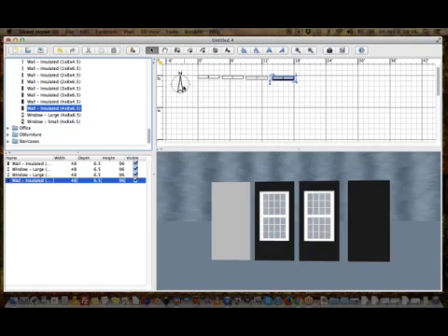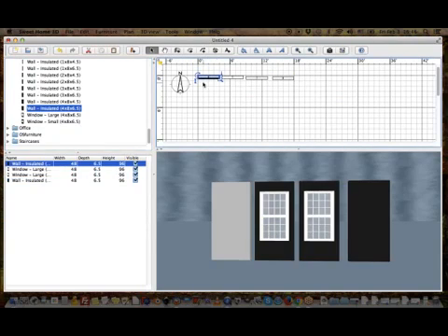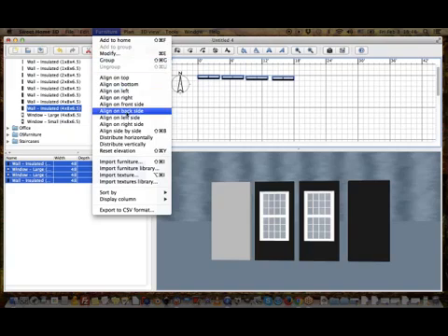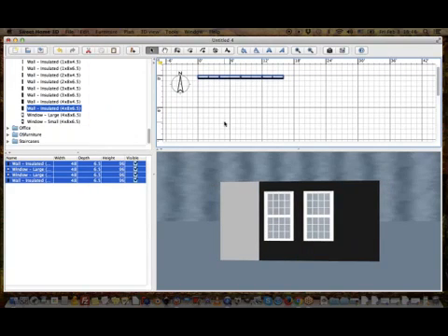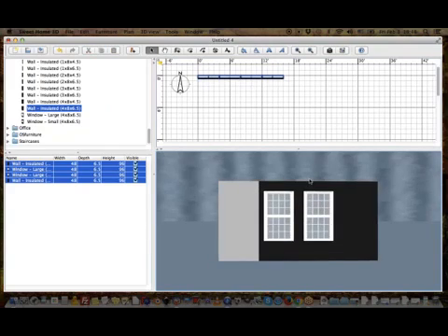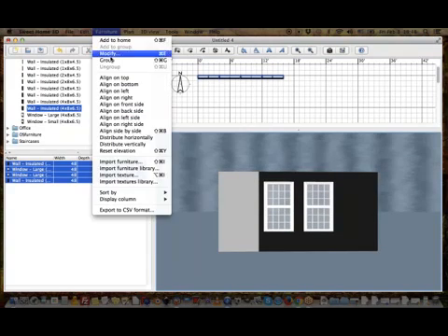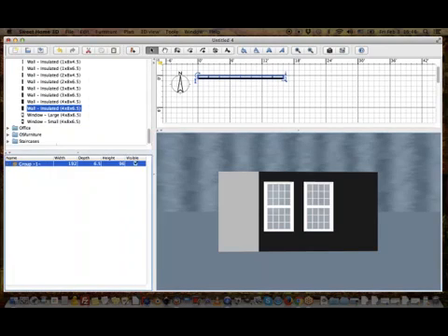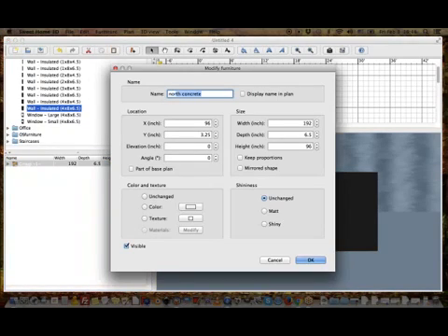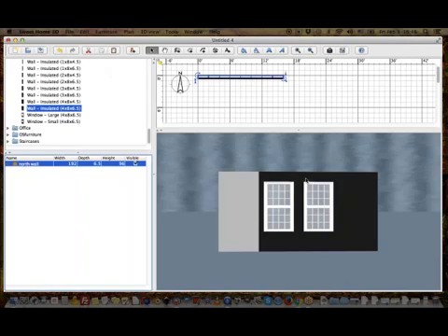If I want to have a perfectly straight wall, I start by selecting the first one. So always start with the one that is already in the position that you want it. And then I select the remaining ones, and I go to Furniture, Align side by side. Okay. And now I got my first wall. We're going to design a very simple structure, just a small one. I'm going to group this just for housekeeping purposes, and I'm going to call this north wall.